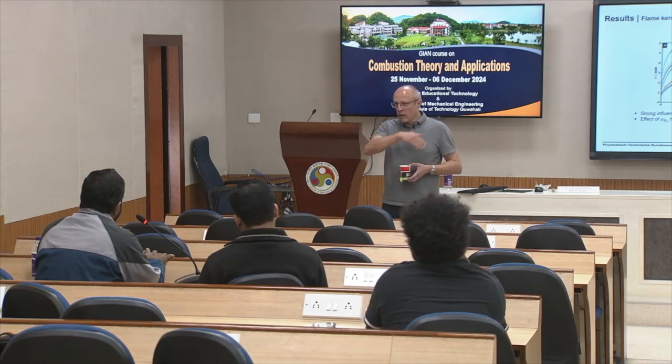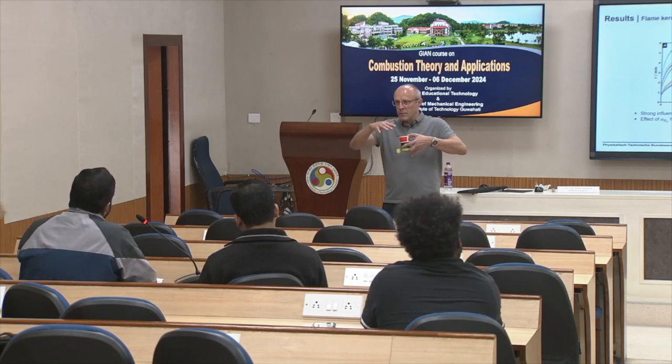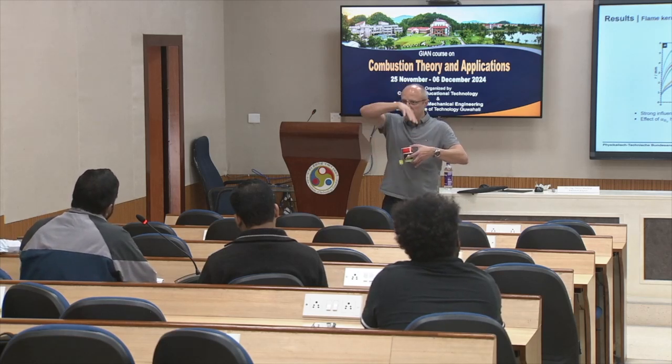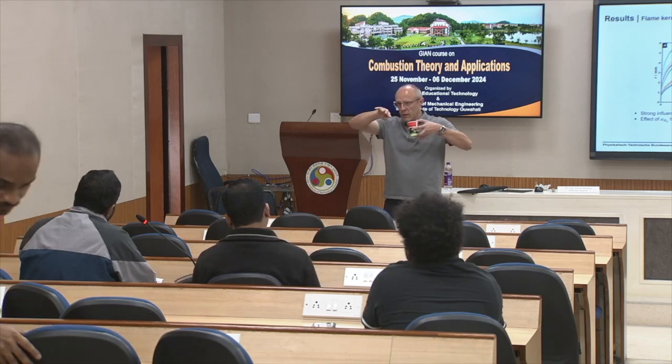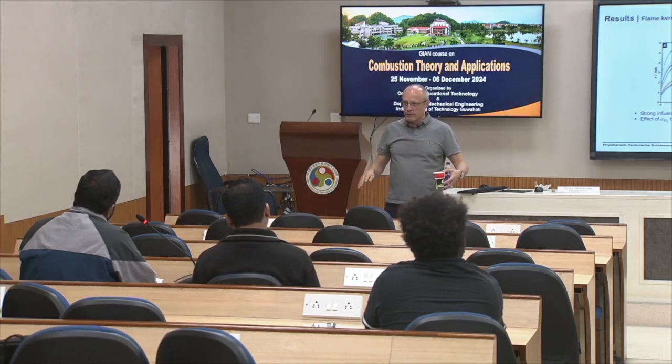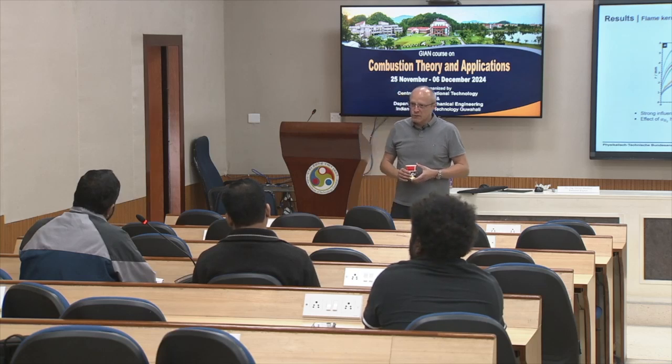But for slow ammonia, you have seen we reach much lower explosion pressures. Because ammonia ignites in the center, then it goes up, reaches first the top side of the vessel, and then the flame goes down left and right. So here, of course, we have strong losses due to cooling.